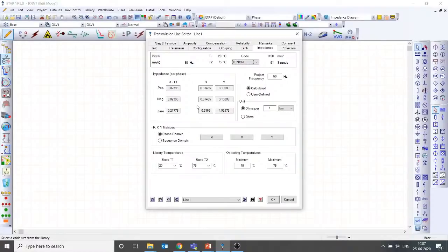But when you go with those calculations, if you have a double circuit, or 4 circuits, or multiple ground wires, etc., then your matrix size will be much more difficult to calculate, but the software automatically provides you the data. So if you are doing something manually, you can very well validate it with this. So resistance, reactance, susceptance, all these parameters I have identified.